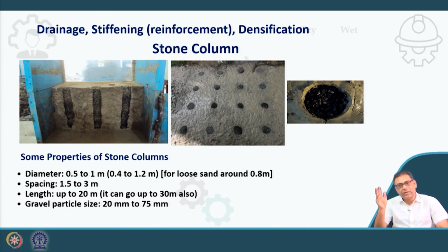Drainage is the main issue, and then it will act as a reinforcement material. So, it will increase the overall stiffness of the soil. But that part I am not discussing here, because that is for soft clay for consolidation purpose. Here, if you use it in loose sand to mitigate liquefaction, that is why we are using it as a mitigation technique for liquefaction hazard.